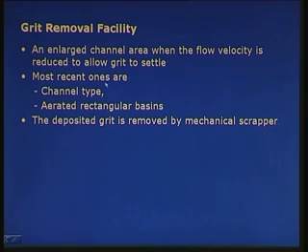This is the enlarged area, channel type, which is just what we discussed: enlarging the channel area, decreasing the velocity, which will enhance the settling of the particles. The second type is aerated rectangular basins.